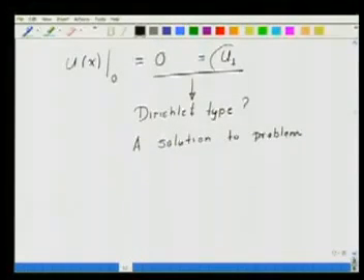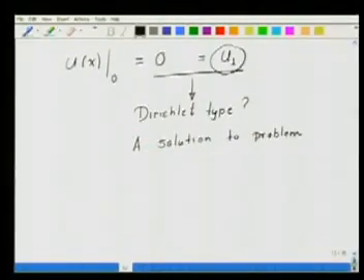And how do we impose this in our code? It is by modifying the equation corresponding to u1, that is, k11 we are going to make equal to 1, k1i for all i greater than 1 we are going to make equal to 0, and similarly ki1 is equal to 0 for all i's. Under this condition we are going to get a solution to the problem.